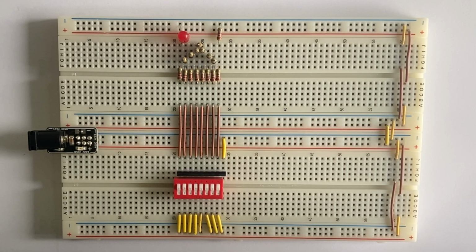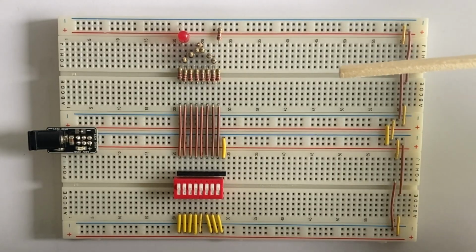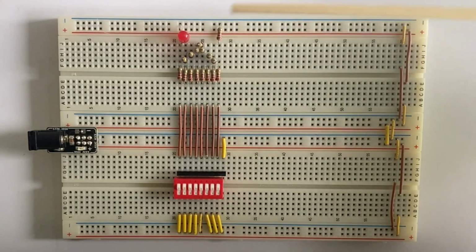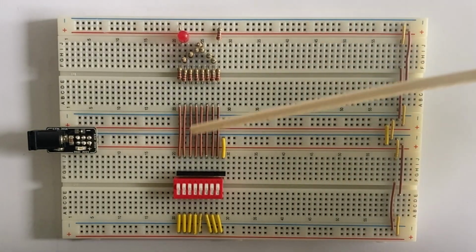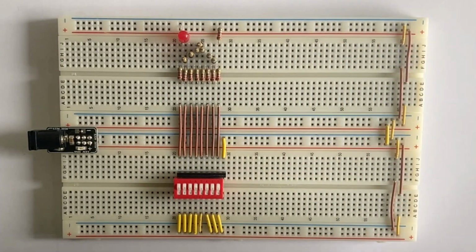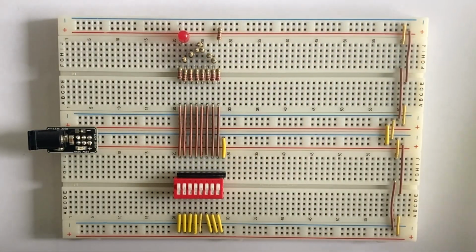Project 2.1, Digital to Analog Conversion. This circuit I have here is a form of a DAC. It's called an R2R ladder. The purpose of this circuit is to take the digital input voltage of 9 volts and convert it to an analog voltage. It splits the voltage into 8 binary bits. As you move from left to right, each bit in the circuit halves the voltage.